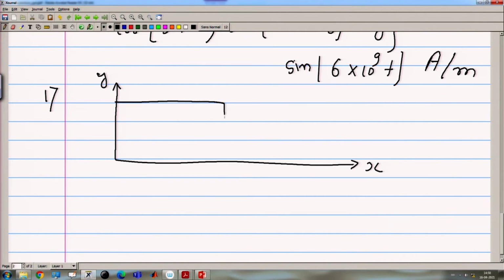In this direction it is A, and in the other direction it is B, and in the middle one probe is there. This is the probe, and it is fed by making a hole; this is the outer coax, this is the ground PEC, and here is the inner probe. That is feeding from this, and the current flowing on the probe surface is I naught.